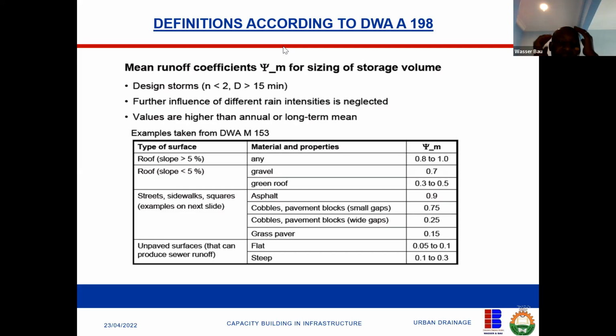Someone says, is the runoff coefficient the same thing as the Manning runoff coefficient? It's part of it, but it's not exclusively Manning. Manning's n is talking about hydraulics, the roughness of the area, which is also part of what we're saying here. Okay.